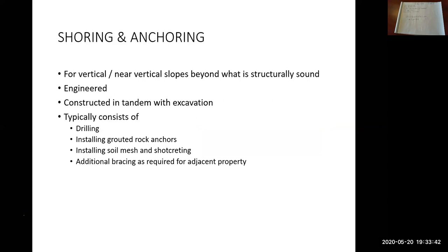Okay, so shoring and anchoring. Used for vertical or near vertical slopes, beyond what is structurally sound. Meaning if you were to dig ground at quite a steep angle, so almost vertical, it would not stand on its own. That would mean it's not structurally sound. It would fall down. It would slough into the hole, which of course is dangerous.